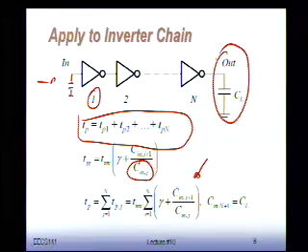That's my big capacitor CL that I want to drive. So we know that Cin,n+1 is equal to CL, and we know that Cin,1 is going to be equal to Cmin, let's say the minimum input gate capacitance. So those are given. Okay? So my goal now is to figure out how should I size those different capacitors, or in other words, how should I size the gates in such a way that TP is minimized.